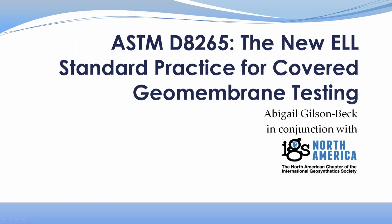So to give you the context of where this new standard fits in, this is a standard for covered geomembrane testing. The only standard that has ever existed for this type of testing is D7007. It was invented in the 80s. It's been largely unchanged since then. So this new ASTM is an improved alternative to D7007 for testing covered geomembranes. It is more stringent.